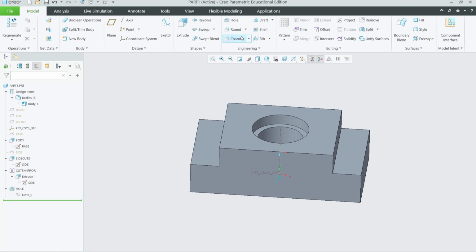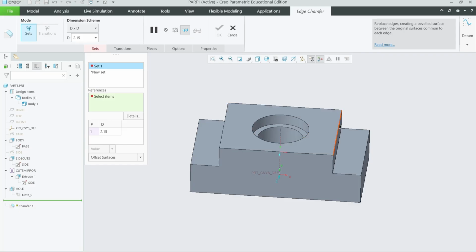First we're going to add some chamfers to the part. Here we're going to select just these 4 edges on the side of the bracket. You can adjust how intense you want that chamfer to be, as I described previously. Here I'm choosing between 1, 10, or 5. I'm just choosing 5, something in the middle, so that it's not as intense, but not as subtle either. We want something that we can definitely notice.